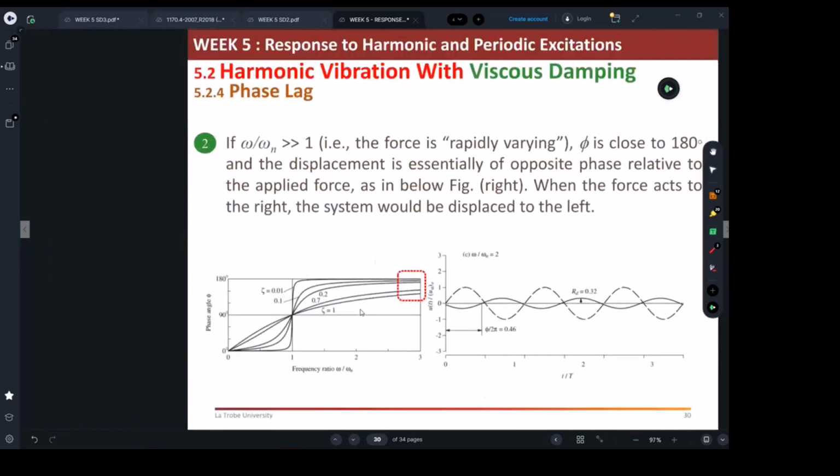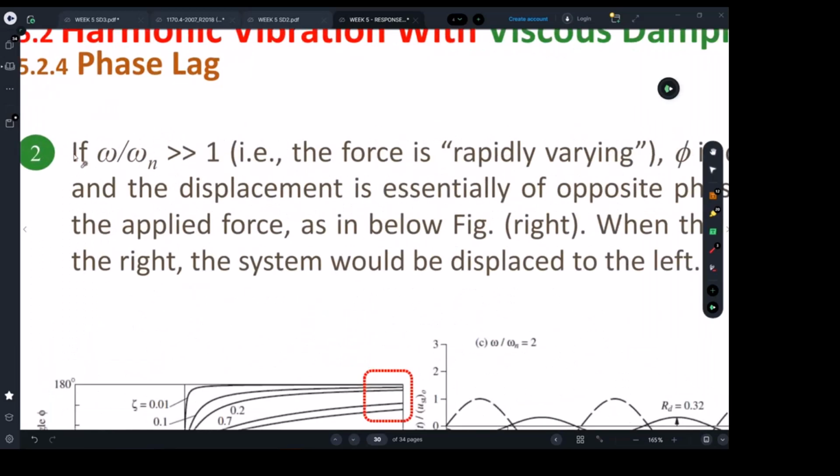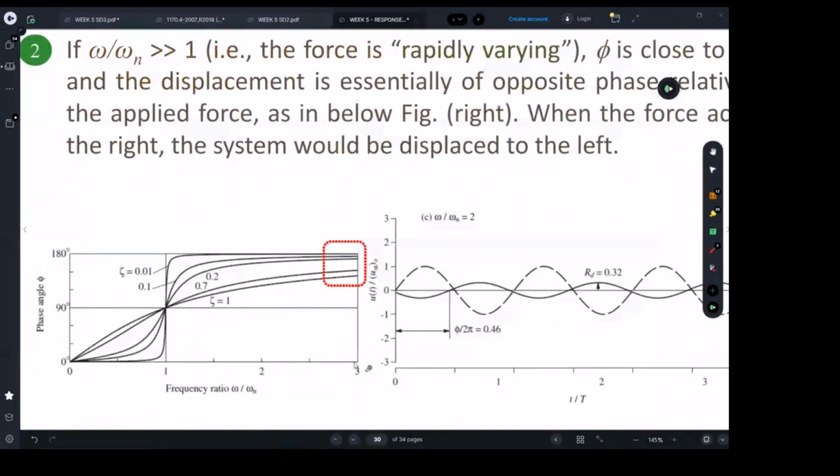That's the first situation. The second situation is the opposite to the one we just talked about. Here it's a soft building excited by a motion with very high frequency. So this is a very high number and this is a very small number, which will result in a very, very large ratio. Where are we going to be situated on this curve? Having a very high ratio, we're going to be somewhere here.